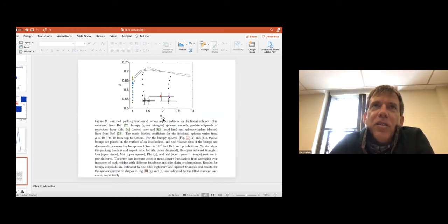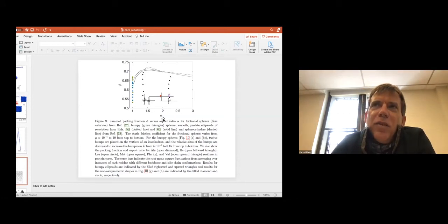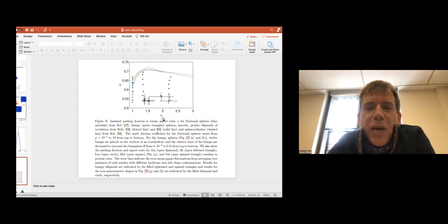And so then you can also talk about spherocylinders to mimic elongated particles, where spherocylinders are made up of a cylinder and then spherical end caps. And then the aspect ratio just means how do those differ from spheres? So how elongated are they? For an ellipsoid, it could be the ratio of the major to minor axis, or for a spherocylinder, it could be a ratio of the length of the cylinder to the radius of the end cap.